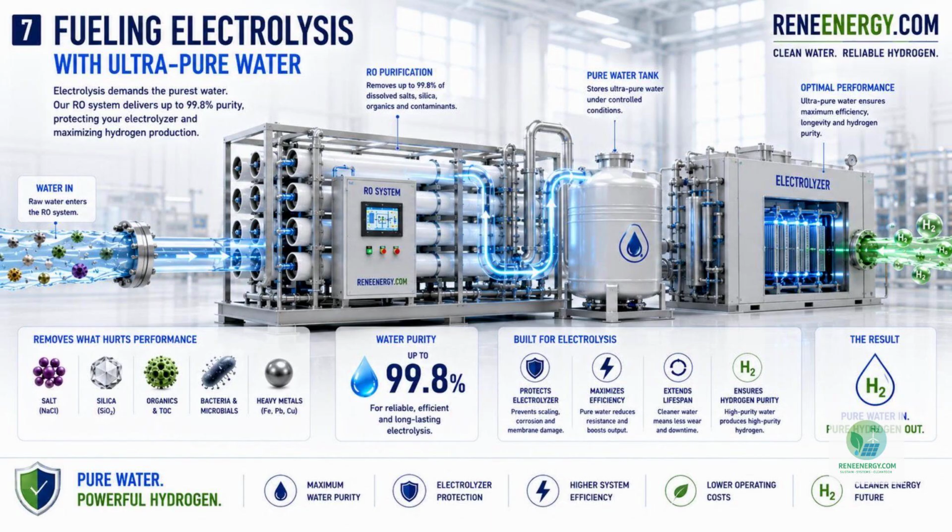This connection is critical. The electrolyzer depends on stable water quality to protect membranes, reduce scaling, maintain efficiency, and produce reliable hydrogen. Poor water quality can increase resistance, damage catalysts, shorten stack life, and raise operating costs. Clean water is not just an input. It is part of the electrochemical performance of the plant.